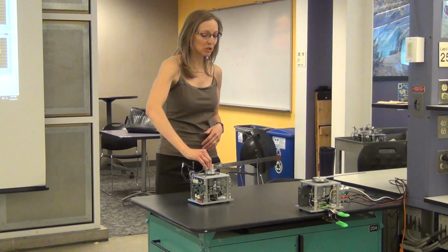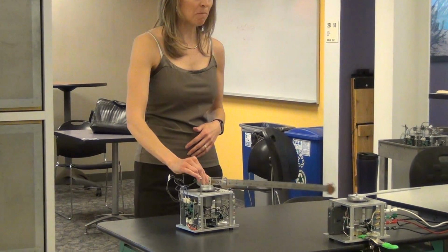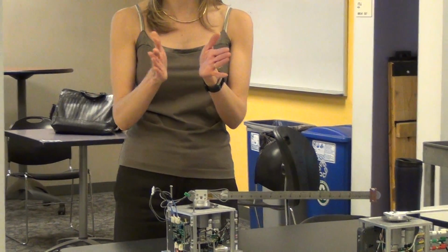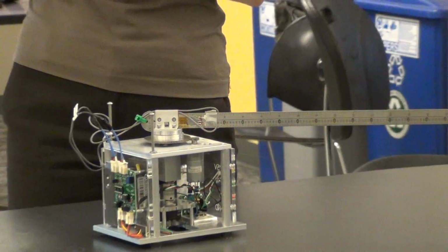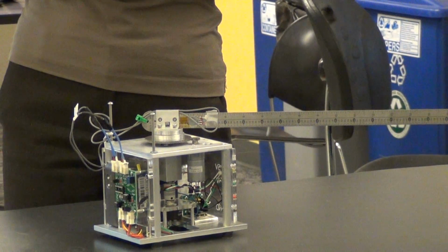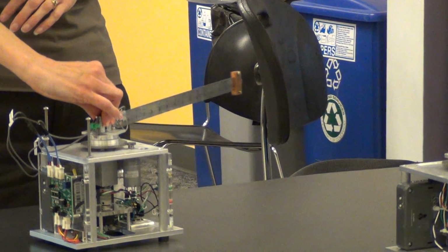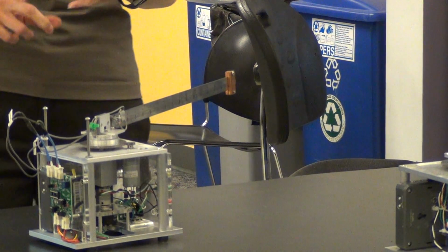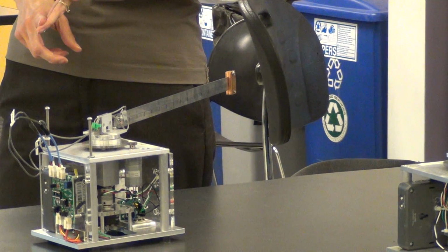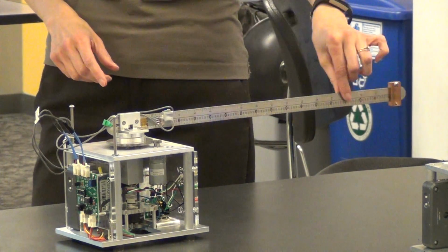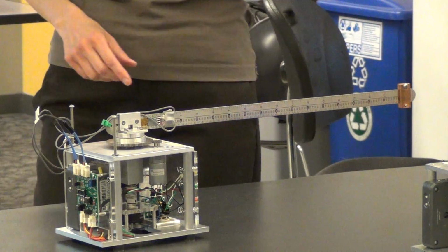And if we move them too quickly, we could bend them so much that the solar panels are actually going to crack and break. So this is where the control gains and the performance are really important. We want to be able to point it towards the sun, but not have it overshoot or oscillate too much to break the solar panels. So this is where your equations are going to get really interesting.